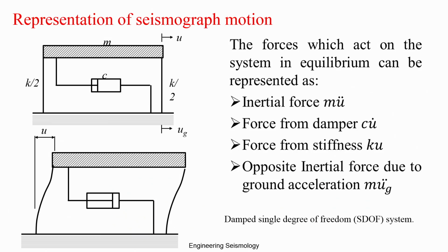Today we are going to talk about the next level of interpretation, particularly time domain parameters interpretation from the seismic record. As we have seen in the seismic instrumentation part, the seismogram works basically as a damped single degree of freedom system, where there is a mass, a damping and a spring constant. When stationary there is no movement, but when there is a displacement, there is a relative movement of the ground.